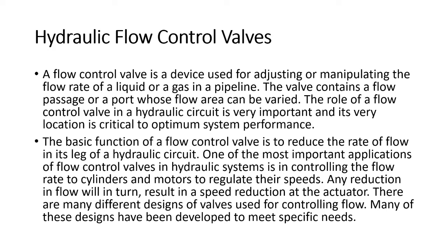The basic function of a flow control valve is to reduce the rate of flow in its leg of a hydraulic circuit. One of the most important applications of flow control valve in hydraulic system is in controlling the flow rate to the cylinder and motors to regulate their speeds. Now, any reduction in flow will in return result in speed reduction at the actuator. Now, there are many different designs of valve used for controlling the flow. Many of these designs have been developed to meet very specific needs.